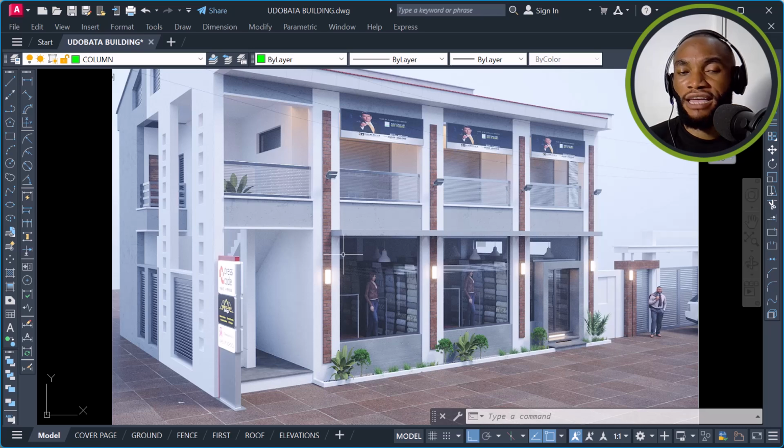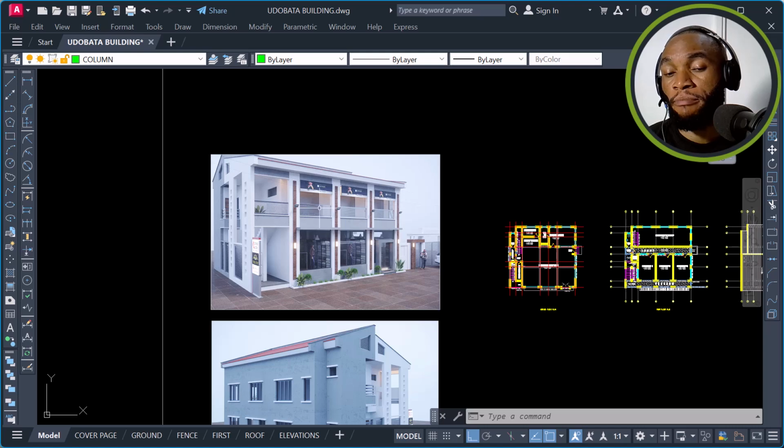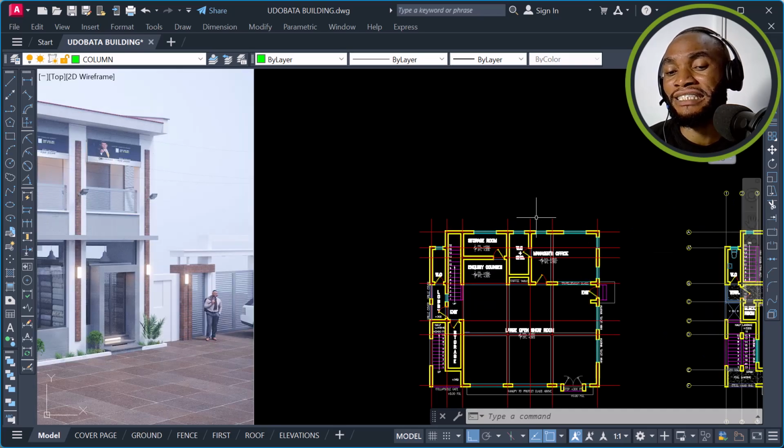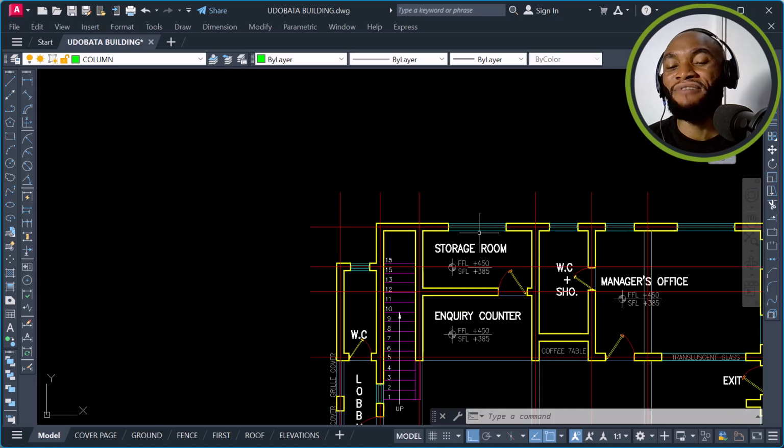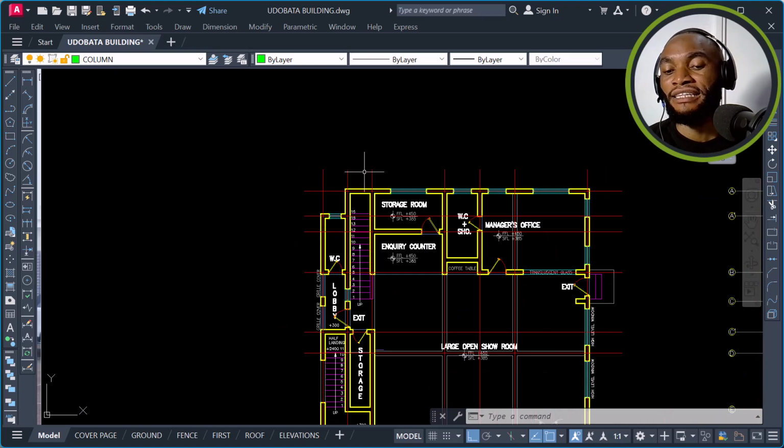Each of these buildings has its own principle on how to choose your structural member size or section wisely. But based on Eurocode, BS code or any other design code, there is a lowest column size that you are meant to assume. Then if there is any failure along the line, you can choose to do what? Increase the size. That's fine.